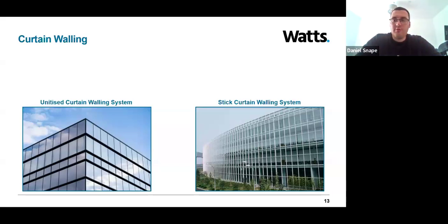This form of construction basically comprises prefabricating larger sections of a curtain wall system, known as units, off-site, and then installing these pre-made units onto the building structure, typically via brackets that you'd see connected to the structural floor slabs. These facade systems are often bespoke in design as well, so they can suit various design preferences and building layouts, which is one of the reasons that they're commonly used.